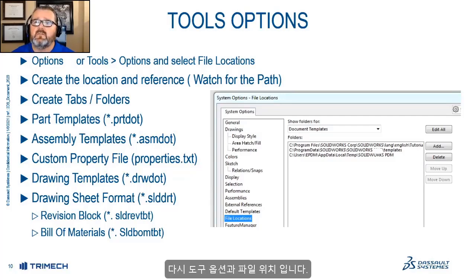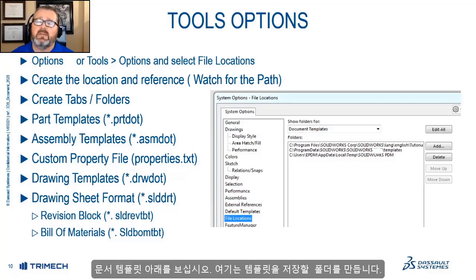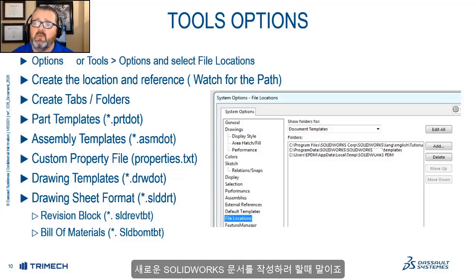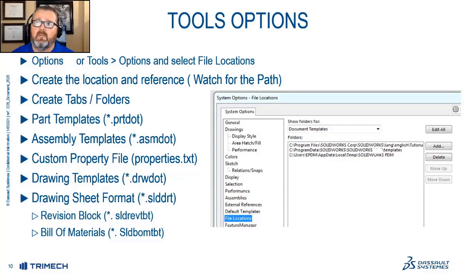Once again, Tools Options, File Locations. Look under the Document Templates. Store and create the folder where you need to place your templates, so when you go to create a new SOLIDWORKS document, it automatically will pop up and show the tab within SOLIDWORKS.